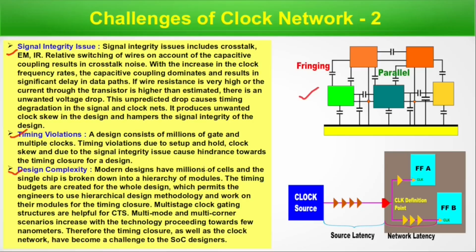Now, design complexity. Modern designs have millions of cells and the single chip is broken down into a hierarchy of modules. The timing budgets are created for the whole design, which permits the engineers to use hierarchical design methodology and work on their module for timing closure. Multi-stage clock gating structures are helpful for CTS. Multi-mode and multi-corner scenarios increase with the technology proceeding towards a few nanometers. Therefore, timing closure as well as clock network have become a challenge to the SoC designer.